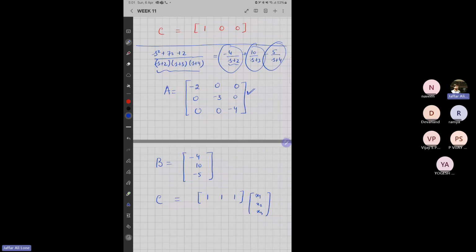Actually, there are many other ways, because I told you there are infinite ways to write these state space representations. So in this case, this is also correct this way, and that should also be correct, I think. Just make sure that if it is from that lecture, it should be correct. And I'll also verify the source and tell you the names of books where this is given. There are many ways. Even there is one more thing: when there is a repeated eigenvalue or repeated pole, then you have to write it in Jordan form. There will be a Jordan block, right? And there will be a 1 in that case if this is -2. So there are also those things. Just go through some authentic books, and I think this will be clearer.